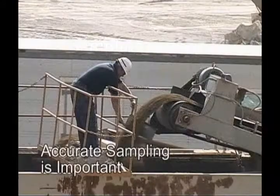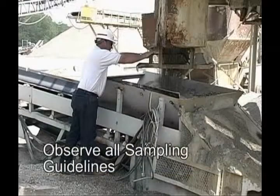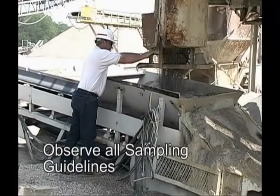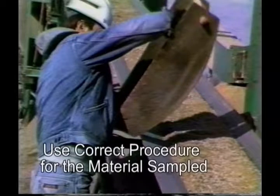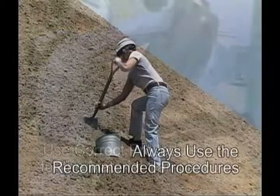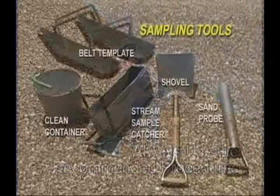No single phase of an aggregate inspector's duties is as important as obtaining a representative sample. Samples should be taken at the proper frequency, meet the minimum sample size, and be randomly obtained. The first step in obtaining a representative sample is to identify the material to be sampled and the correct way to obtain the sample. If you are not able to determine the correct procedure, contact your materials office for recommendations.